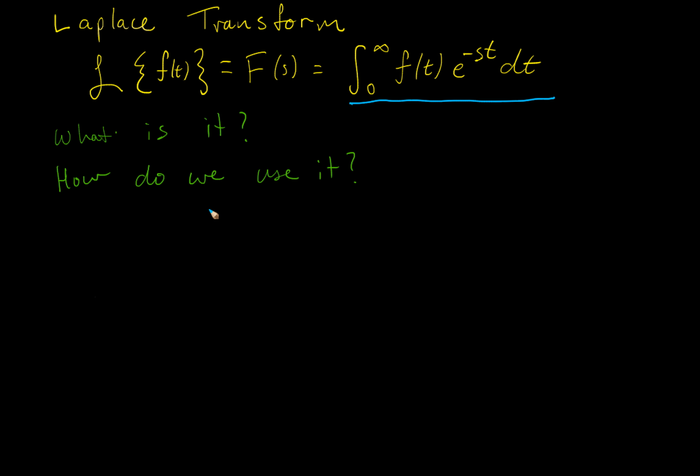So we might have an ordinary differential equation like, say, second derivative of y plus 3 times first derivative of y plus 7 times y equals, say, u dot plus 2u. So here u is some forcing function and y is the output that we want to study. And these are just numbers I kind of picked out of the air. So what good does the Laplace transform do? Well, what it does is it converts a differential equation into an algebraic equation.